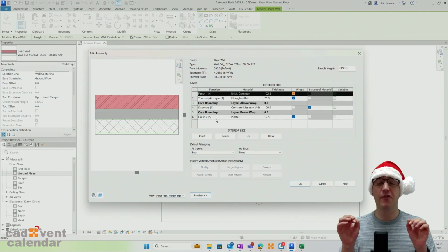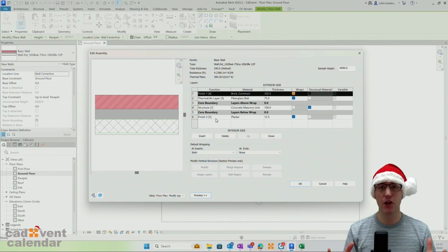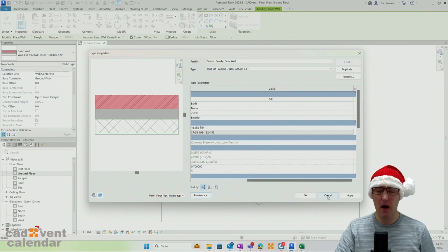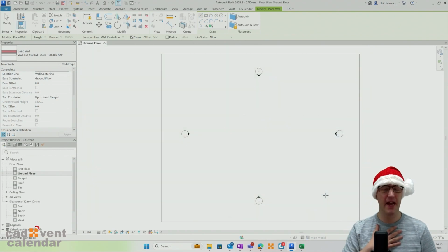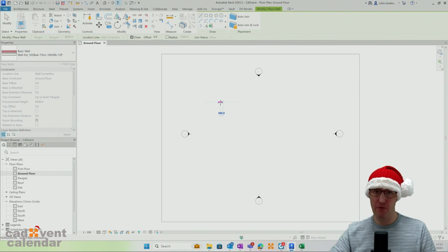And absolutely you would spend time within your template creating your own layers and walls to represent the components that you're going to be drawing. I have the really lovely job of saying I don't need to worry about that. So I'm just going to draw using the out-of-the-box walls, but you do what you need to do and follow along. From there, we simply start drawing. I click once in my drawing area where I want to start drawing my line, and typically I draw left to right.